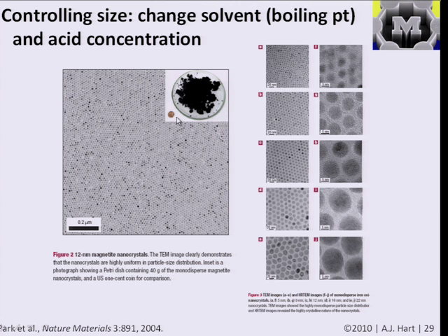And it turns out that the process of packing, kind of like we saw for nanosphere lithography that we introduced before, is highly dependent on the standard deviation or the monodispersity of the particles. You get a lot better packing if the particles are more monodispersed. And so processes like these that make highly monodispersed particles are necessary for getting them to self-assemble and pack with high order over large areas. And that idea of packing is kind of why you see that some of their TEM grid images not only look very uniform in size, but also have the particles nicely packed together. So that's a practical ramification of the ability to make these particles with pretty uniform size distributions.